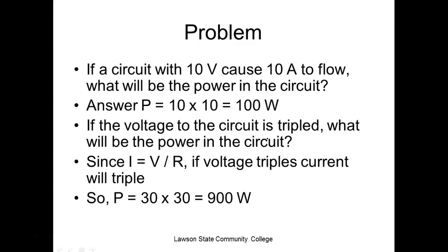Because if my voltage halves, I think I tell the story about my mom and her stove. Her electric range wouldn't boil water anymore. Well, she lost one of her feeds on her 240, so her heating elements were only getting what? 120 volts. Well, the power dropped down to a quarter of that.